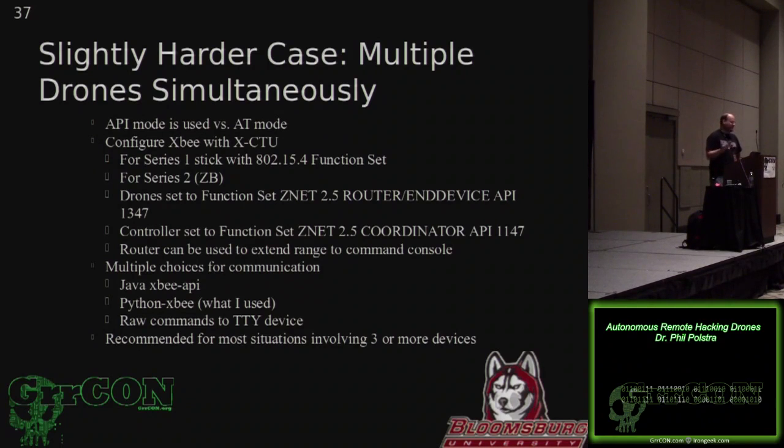and again, you do the same thing. You use the XCTU or iron in order to configure your modems, and then you put it into API mode. If you're using a Series 2 adapter, you have to tell it what it is and have to load up the firmware, which you can also do in this XCTU software. So what you do there is you have to have one coordinator device in every network.